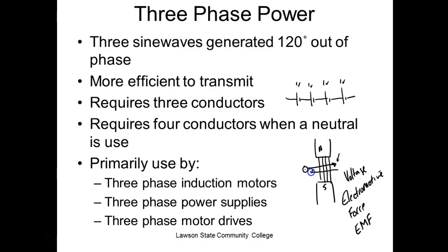If it comes back the other direction, I'm going through the magnetic field again, and the current would reverse, but we would produce the same voltage. So what we do is loop the wire. Every loop is going to induce a little voltage, and they're wound in the same direction, so their voltages would add. So what happens if we hook batteries in parallel?